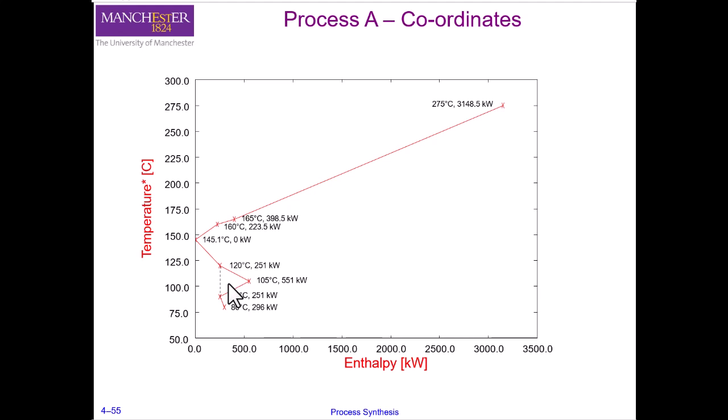Now we are going to look at which streams we can extract in terms of the cold streams and the hot streams. Cold streams will need steam heating from our utility system, and our hot streams below the pinch can be used to generate steam.